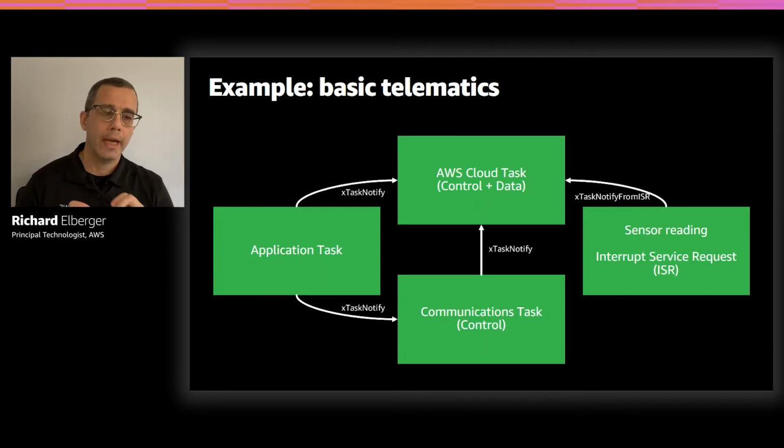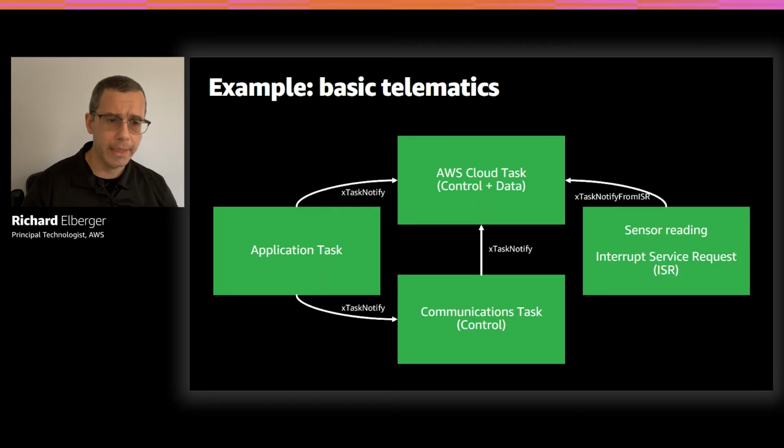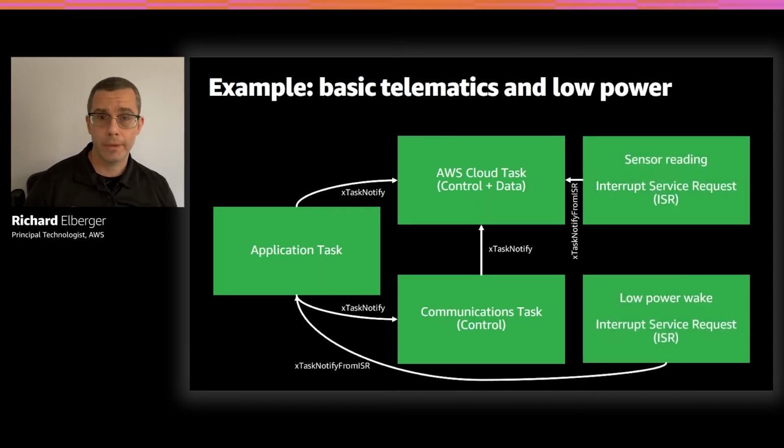So now we know how we're communicating from the sensor through some required mechanisms and then to the AWS cloud. But there's one more thing I'd like to touch on now, and that is the low power mode. All right, super important. What happens when we go in low power and we're dealing with this communications? Well, let's see. What can we do? We can put the module into a low power or a sleep mode. Okay, and if we do that and the module can't send data, what's going to happen? Well, the socket connection is going to close, right? So when we're in low power mode, nothing is going to be sent to the cloud at all.